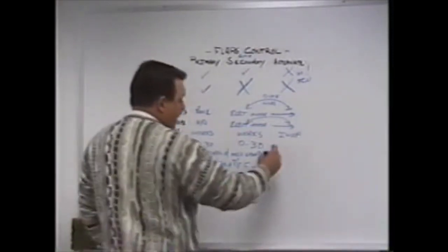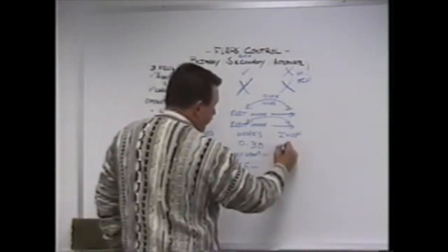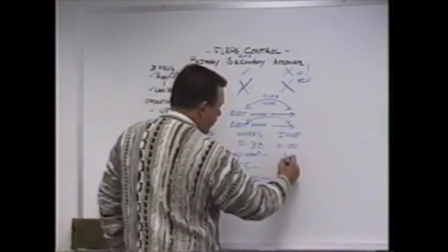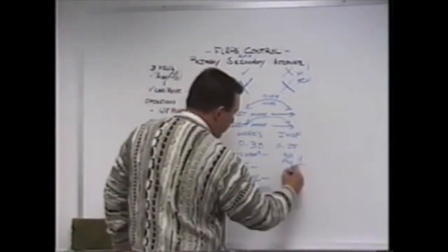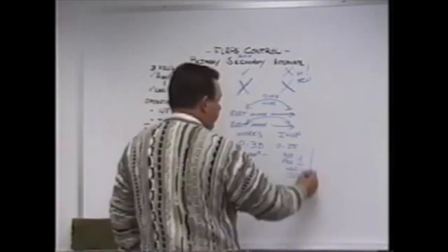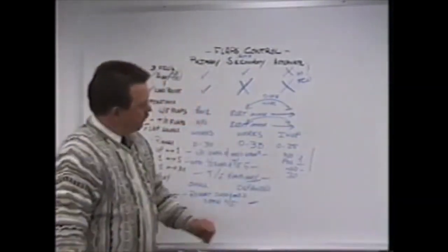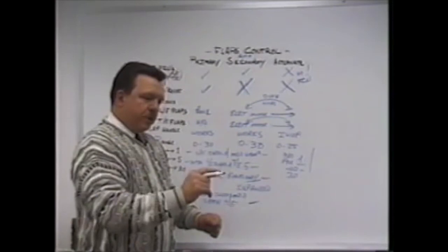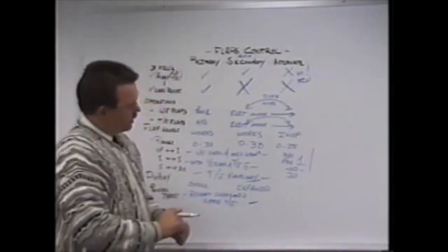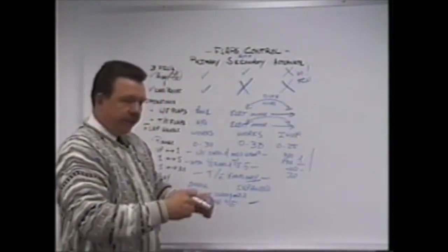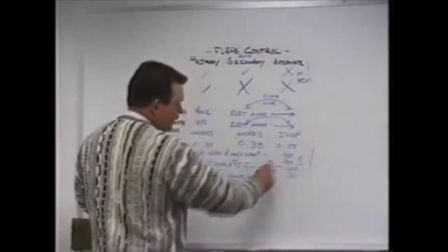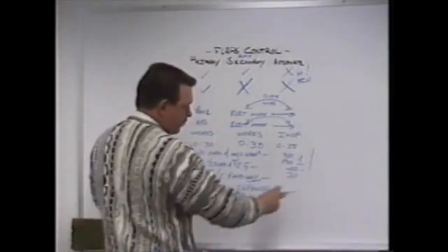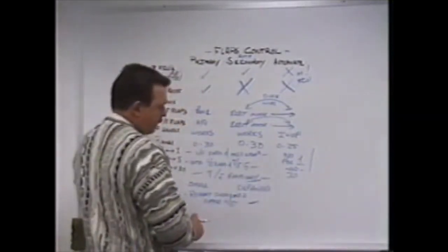What range can you select on the alternate mode? You can go from 0 to 25. There is no position 1 or 30 on alternate trailing edge flaps. Because when you take the arming switch to arm and then take your switch to extend, all the leaders and all the trailers come out at the same time. So there's no way to get partial leaders. Also, the flaps will automatically stop at 25, so there's no way to get to flaps 30.